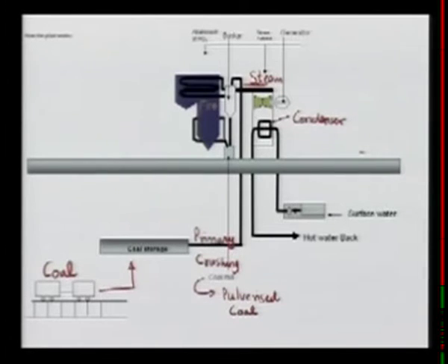How the condenser really works, because this also has environmental issues. You take the surface water, or it could be the water from the sea. Suppose there is a river here, and you are pumping the water, and provide a large surface area, and this cool water, which is relatively cool, comes in contact, not the water but the surface, which comes into contact with the steam, and the steam, as a result, will condense, okay, and make the water here, and this cooling water is in a closed circuit here.